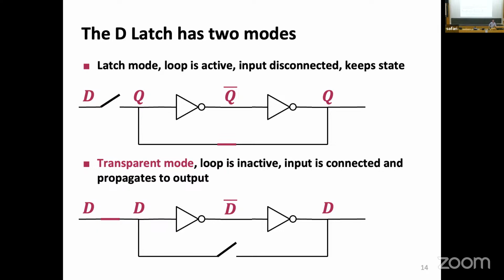Why do I need the NOT gate? Well, first of all, a very fair question. The NOT gate is the easiest gate we can make. It's just two transistors. There is nothing easier we could make. So if I'm making any active circuit, meaning any circuit that amplifies the input signal and restores it again at the output, this is the simplest, smallest thing I can do.